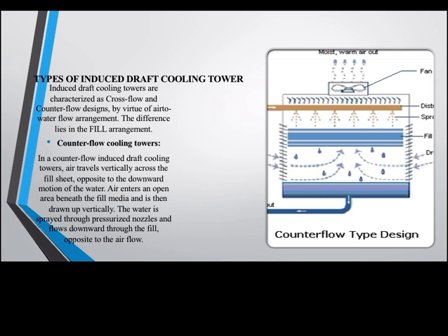In this counter flow cooling tower, the air travels vertically upwards. You can see the air traveling vertically opposite to the downward motion of the water. Air enters an open area beneath the fill media. So this is the fill media and air is entering beneath it and is then drawn up vertically.